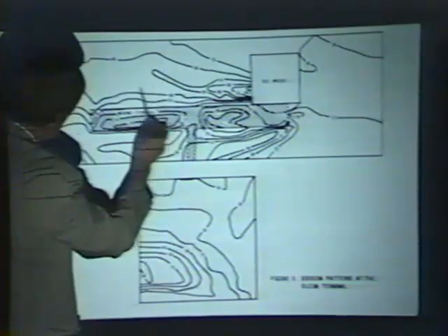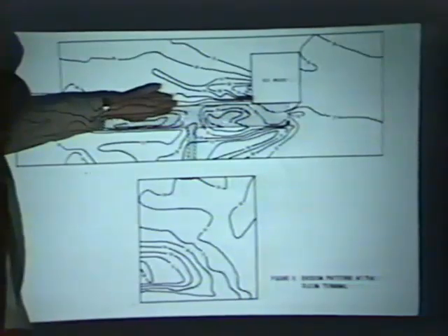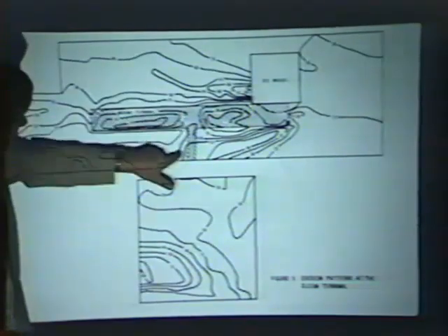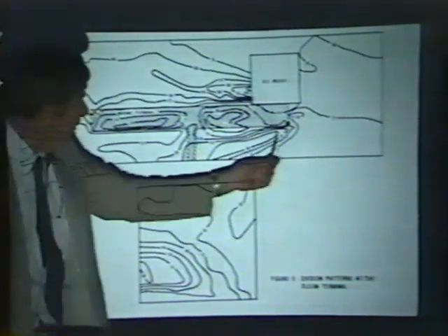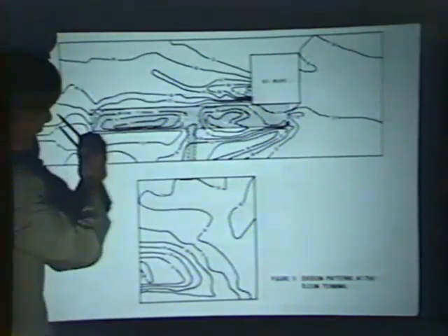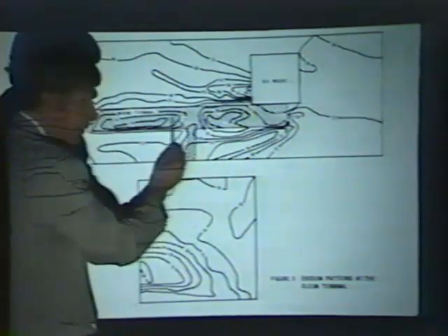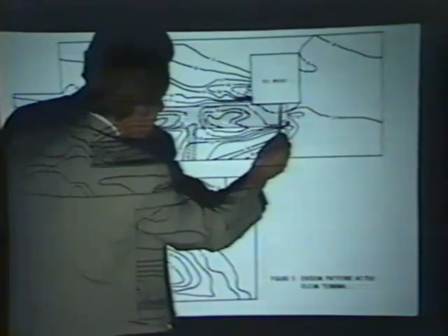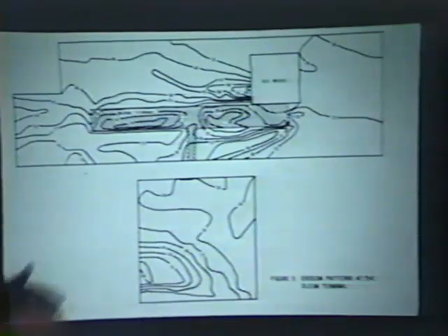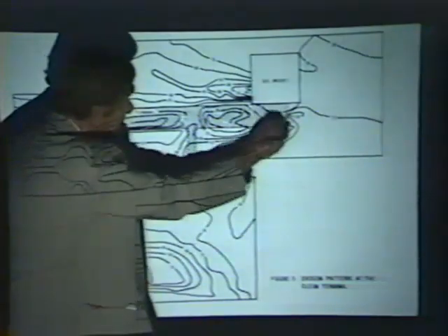Well, why is this peculiar scour occurring? The reason is that there's strong flows out of Carquinez Straits, as I indicated earlier. There's 1,000-some piles underneath this platform, and the sediment accumulated in the piles in the shape of a big loaf of bread. You know, it just filled in the piles, so that this is essentially a solid block out here, and the blunt end diverts the currents on either side and causes these scour holes, but there's nothing to scour out the sediment inside the scour holes.